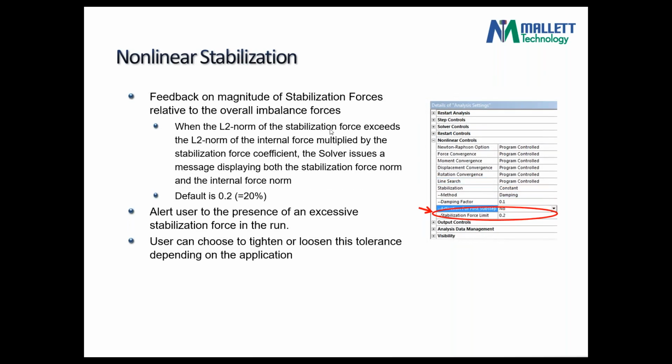So when we apply it, as the program is solving, you are talking about some forces. That's what's called stabilization force, to control the motion of the structure and the various degrees of freedom. We want to make sure that these forces are under control in terms of value. How much of it can you allow and accept, and your solution is still acceptable? Well, that's controlled by what we call the stabilization force limit. 20% of the L2 norm. What is that? Well, the L2 norm is a measure we use in the analysis. So I look at, we look at.